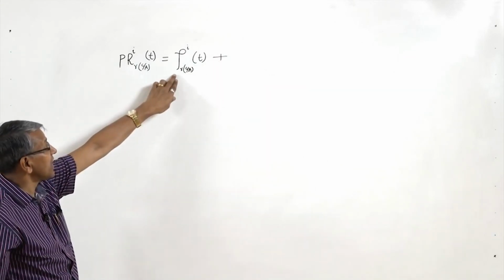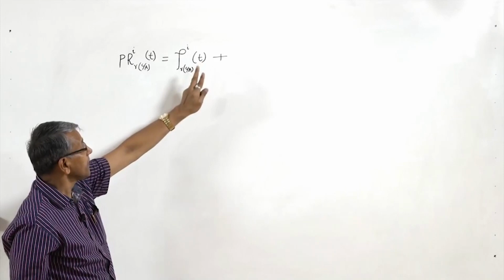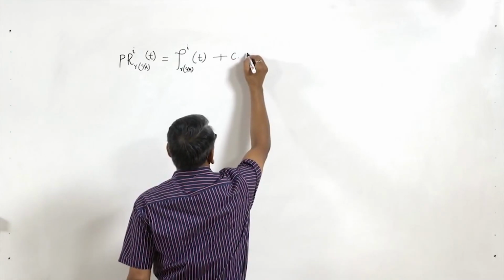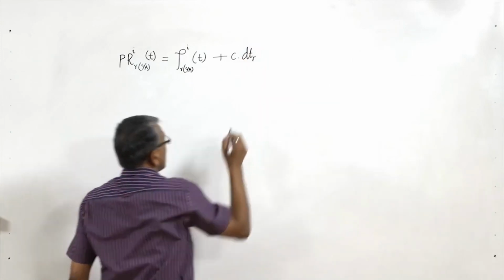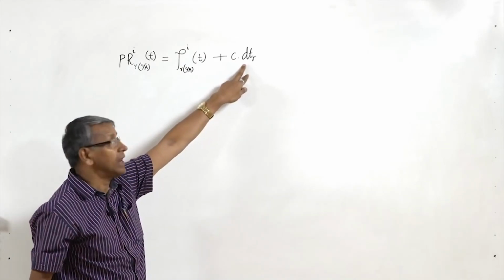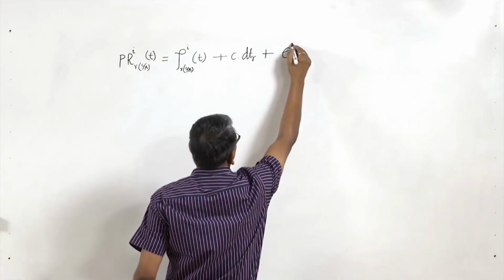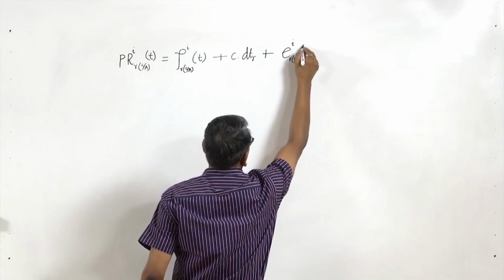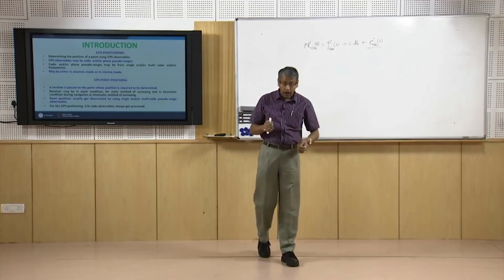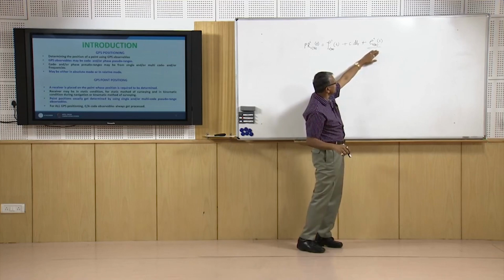This represents the geometric range of the satellite i to receiver R at an epoch t, with respect to the CA code observable, multiplied by, along with this we have the velocity of propagation of the signal multiplied by the error in receiver clock and the error associated with the observable, and this error contains the residual error that is present even after preprocessing as well as random error.